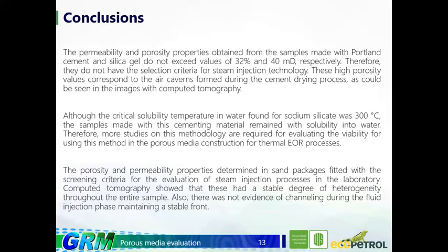Also, the critical solubility temperature in water found for sodium silicate was around 300 Celsius degrees. The sample could not reach this critical solubility temperature and remain with solubility in water at this temperature. Therefore, there is a need to make more studies on this methodology to evaluate the viability of using these methods in porous media for thermal EOR processes.